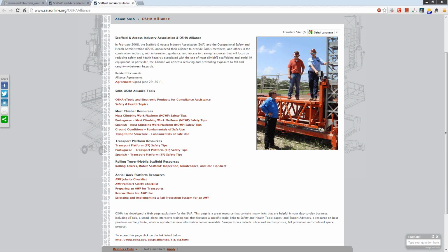We have three questions, and you know what this question is. It's about fall protection, and it's on transferring or leaving the work platform. Three questions, maybe I'll run through them real quick. Is it okay to exit a scissor lift for roof access? What situation would that be okay? Is it okay to leave the AWP to access a higher level? And is it permissible to transfer from an AWP to an adjacent work platform? All three of those questions have popped up.